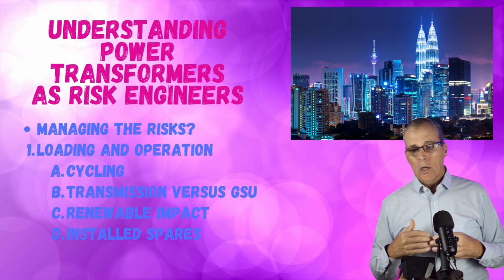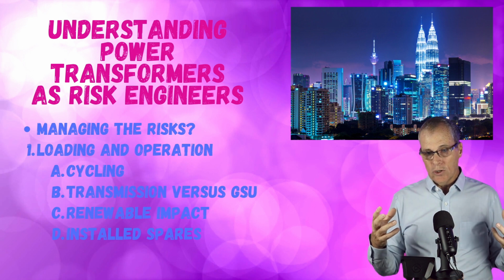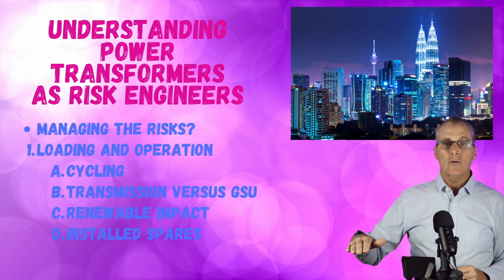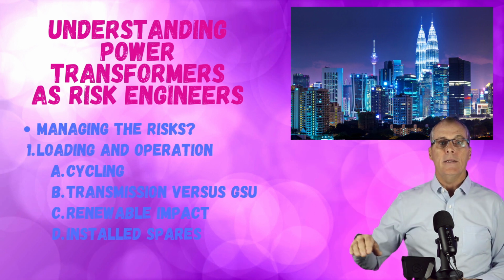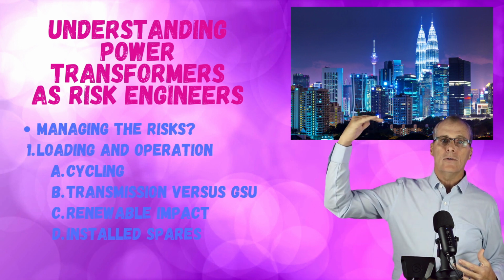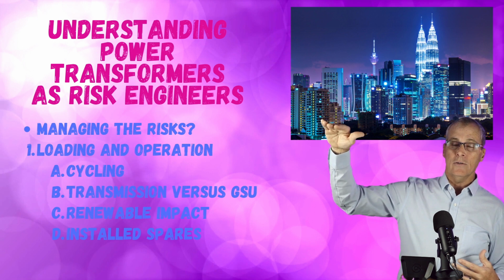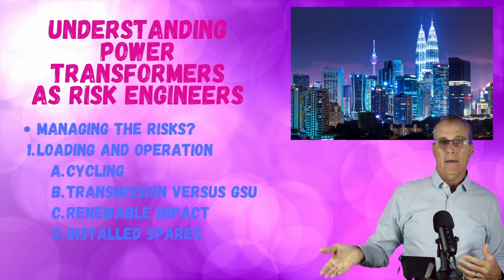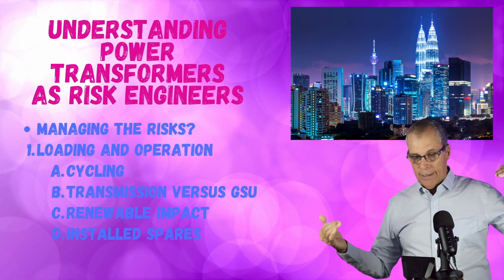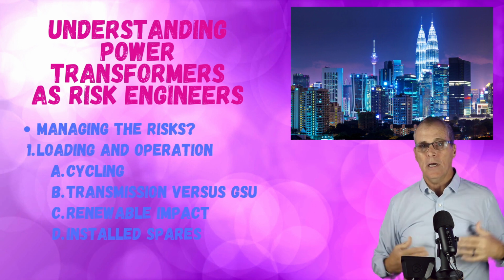Okay, so when would we cycle? You would cycle if you were in a situation where you were providing the GSU for a power plant that cycled. So that transformer has to match whatever that plant is doing. And that can be a solar plant. Every time a cloud goes past the solar plant, the output goes down and then it goes back up when the cloud goes away. That GSU is responding to that, in real time. It has to make up the voltage difference to stay on the grid, and it's going to start to accumulate heat in each one of these cycles.